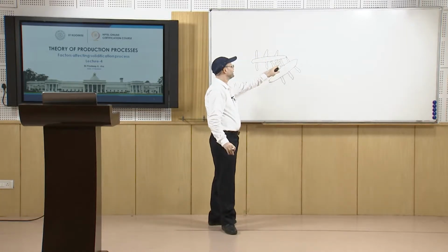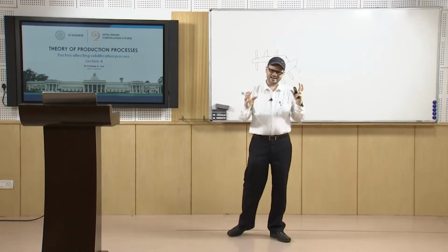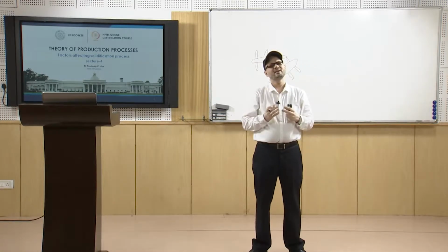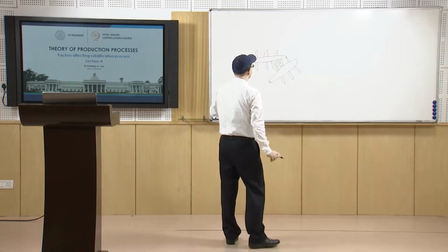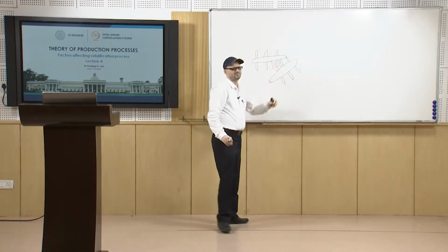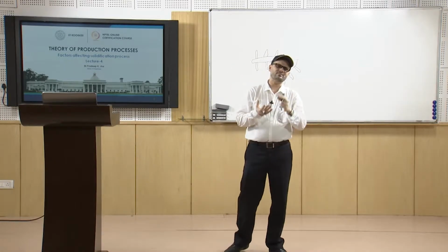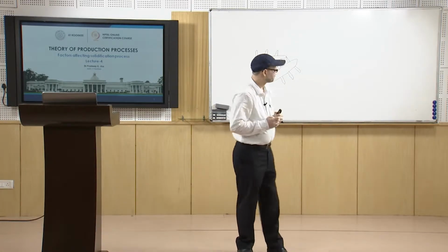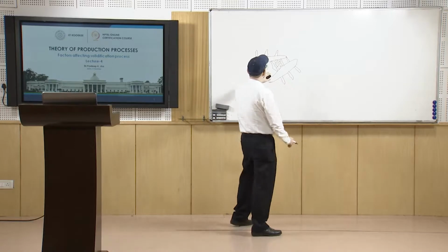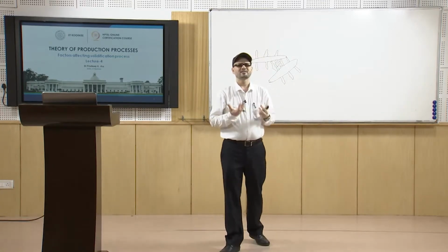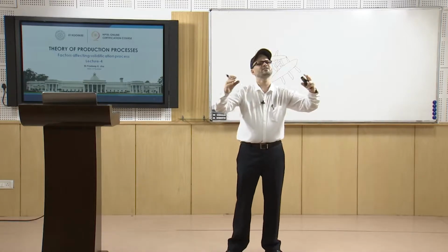So, there is a chance that these are sources of defects, with entrapment of liquid metal in isolation, and that may lead to shrinkages. We cannot avoid it, because this is the trait of an alloy which has a freezing range.